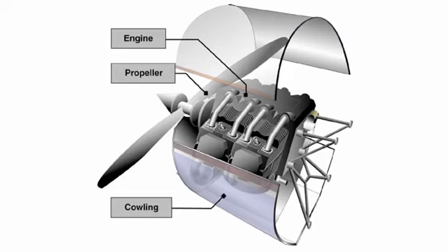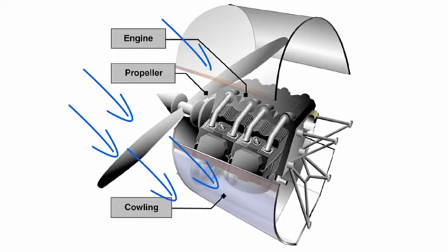A propeller is a rotating airfoil that produces thrust through aerodynamic action. A low-pressure area is formed at the back of the propeller's airfoil, and a high pressure is produced at the face of the propeller, similar to the way lift is generated by an airfoil used as a lifting surface or wing. This pressure differential pulls air through the propeller, which in turn pulls the airplane forward. Propellers are usually matched to a specific aircraft and power plant combination to achieve the best efficiency at a particular power setting, and they pull or push depending on how the engine is mounted.